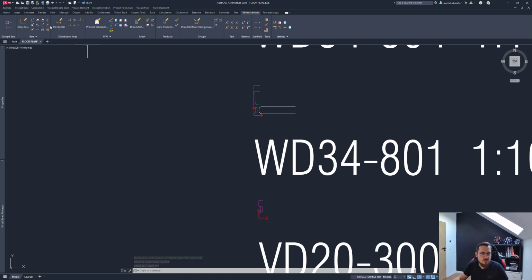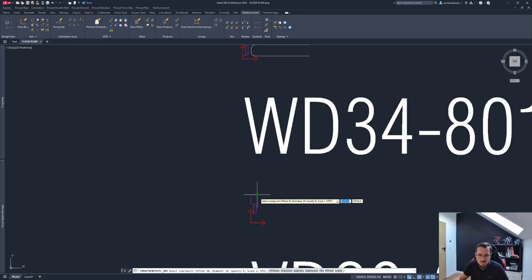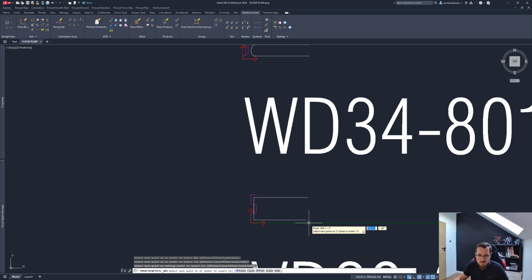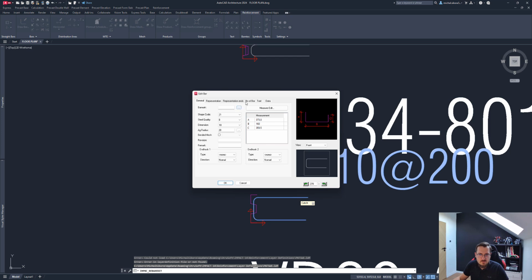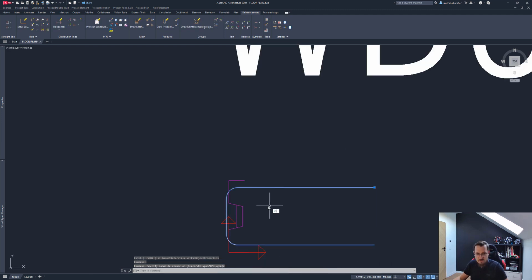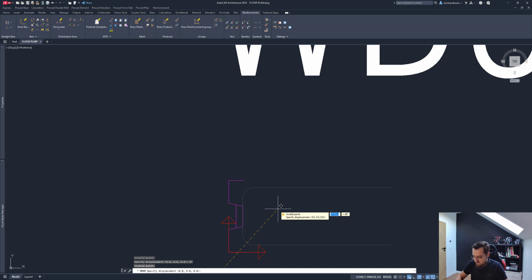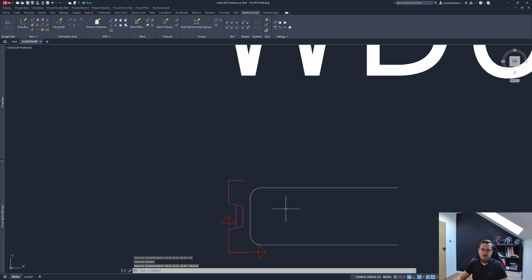What I will also do is very quickly create another bar for us like that. Click, click, click. I don't need to change any settings. Settings are remembered from the last bar. So let's edit that as well very quickly. First, let's turn off the text. We don't need that. General, let's go again, 400 and 400, right? All right, and let's accept that. And I will move my bar to here. 20, 0, 0. Okay. Yeah.